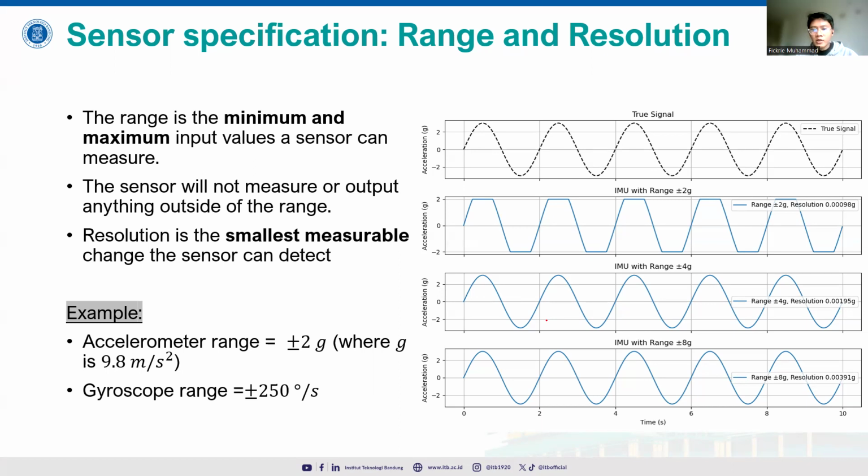We have to check the data sheets before we use our sensor in the first place. The first thing we have to consider is, of course, the range and the resolution, and whether it's applicable to our system. For example, if we are going to use an ROV that will be working in different water property states, such as different salinity, which also means different density and pressure, then the G may fluctuate a little in those kinds of areas, and we have to pay attention to that.